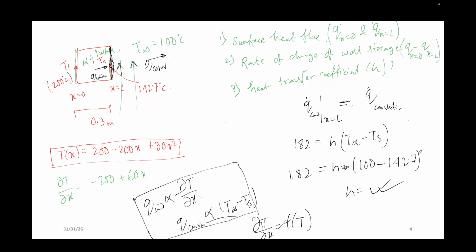So this is your mixed boundary condition. In the mixed boundary condition, sometimes it happens that there is radiation. If the question says that radiation is happening, with convection, radiation is also happening, so another term will come. Why is radiation added to this convection side? Because at the surface, the heat flux is coming, and this heat flux is released because of convection and radiation. That's why this radiation term will come.